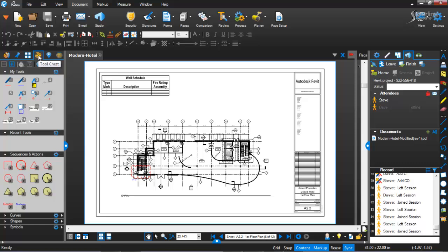There's also a graphical view, and the most important thing that's involved with Bluebeam is our Tool Chest. It's a really important thing, and they've come out with it in the recent versions. This allows me to store any tools that I use on a regular basis. As you can see, there's a My Tools section here where I use highlights, text box, callouts, dimensioning, and signatures. I've got a bunch of signatures here. If I drop that in here, I now have a signature that I can size up and down. And believe it or not, when I print that, it actually prints out really well. So let's delete that. And of course, there's other options here that I'll get into later.